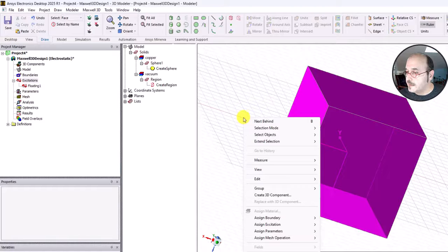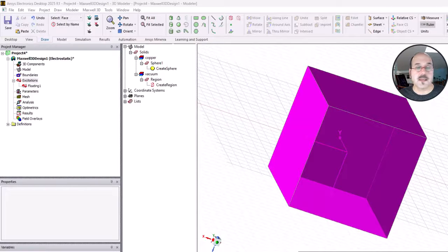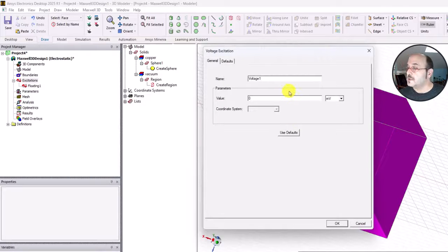I'm going to right click, and then if I go to assign excitations, this time I'm going to choose a voltage excitation. And over here on my second monitor, I got this window that came up. Turns out these default values I'm fine with. I want the voltage of the air box on the outside at the very edges to be 0. And it's basically the same as approximating, as if we go out to infinity in the real universe. I'm saying make infinity close by. And that should give us enough of an area to evaluate fields within that same 100 millimeter radius that we did earlier in the analytical part without corrupting the results. And I'll explain that as we get there later on.